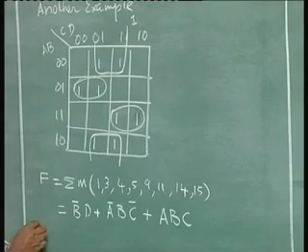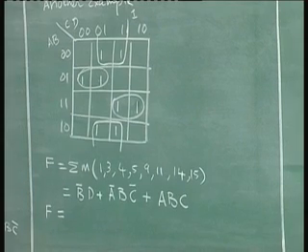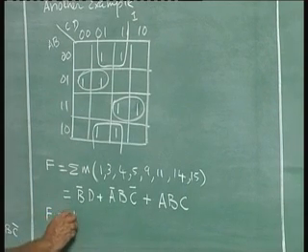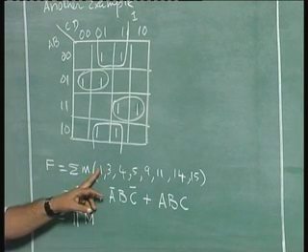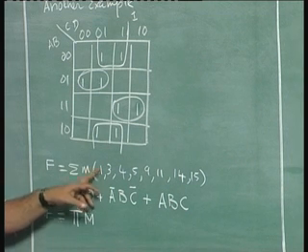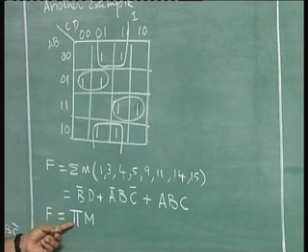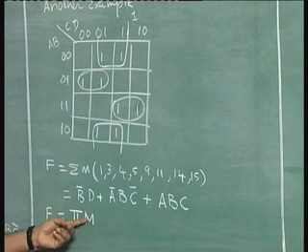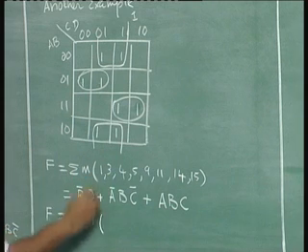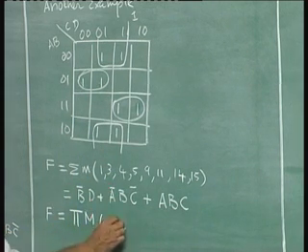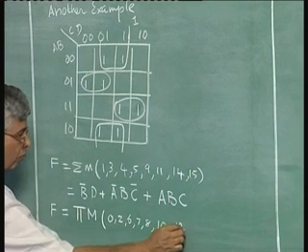On the other hand, if I try to use my zeros in the truth table, F would be wherever there is a 1, all other terms have to be put in this. So you represent this as sum of products. This is a product of sums, so we will put a product, which is a pi, capital M for max terms, small m for min terms. So what are the max terms that will be there? Whatever term is not here will be a max term. So there will be 0, 2, 3, 4, 5, 6, 7, 8, 10, 11, 12, 13.